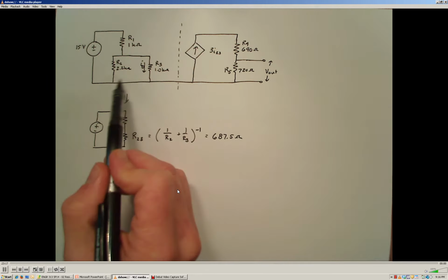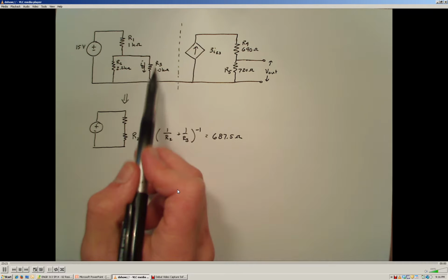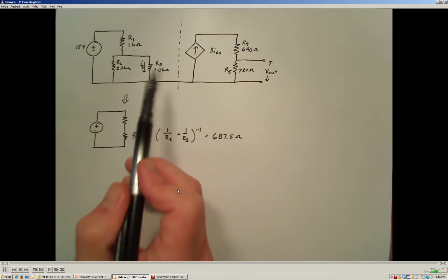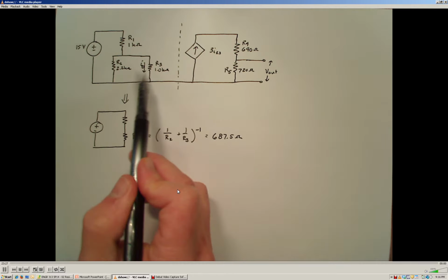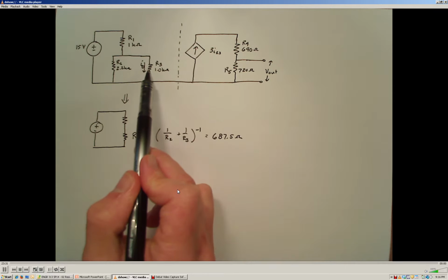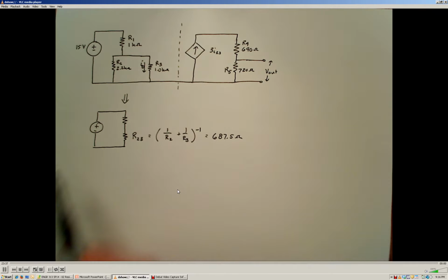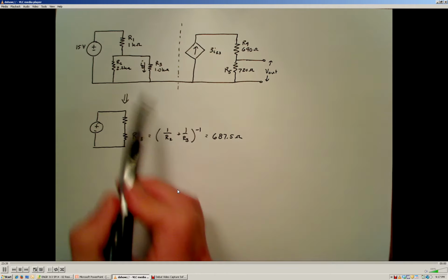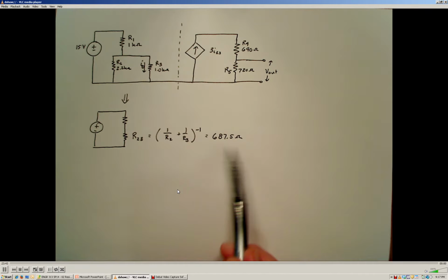We have two restrictive paths for liquid to flow through. And since there are two possible paths, the combination of those two paths provides a wider area, or less restriction to the flow, than looking at a single resistive element or a single pipe. So in that case, since we're combining these two in parallel, it's going to look like there's less overall resistance in that path.